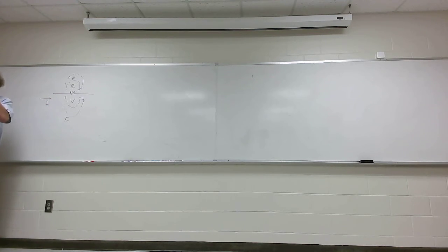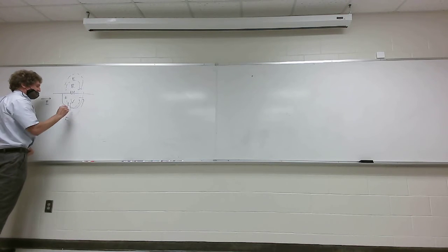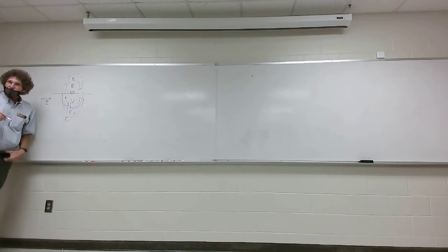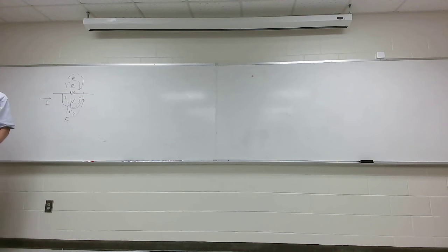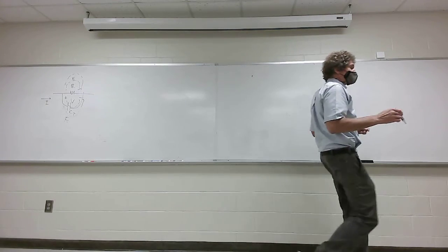Anytime you think about a voltage difference between two points, think about a capacitance. That means there's an effective parasitic capacitance, C parasitic, between those two points. I'm going to model this in a second. Does that make sense to everybody? It's just a reality. You can't get away from it. Now here's the next part, which is dependent on the way the resistor is built.